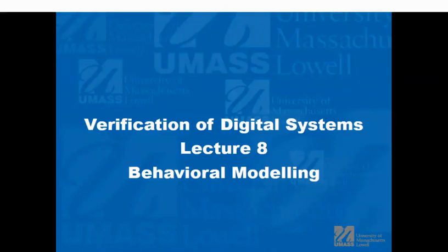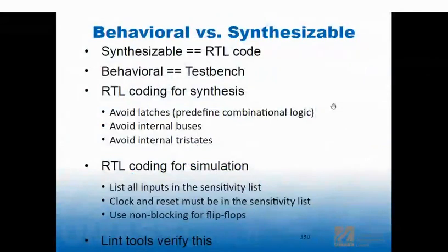So we use SystemVerilog for RTL, and we're using SystemVerilog for behavioral modeling, conventional Verilog, either way. VHDL, same thing. You can use VHDL for RTL, which happens a lot, and you can use VHDL for writing behavioral models for test benches. That's not that common, right? SystemVerilog is the much more common language for test benches, and that's partially because of UVM as well. So as a review, synthesizable code is RTL. Behavioral code is our test bench. RTL code is the kind of thing that we want to develop for synthesis. So we're building architectures, and that's the other class. That's the FPGA class.